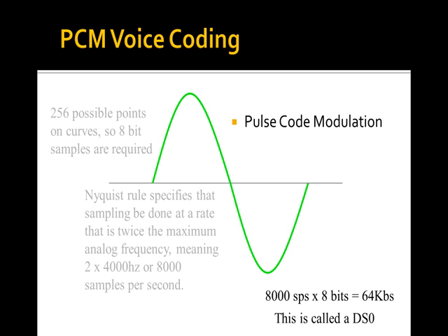So now, we've taken an analog audio signal that matches what's moving on the public switch network. We have coded it to a digital form that we can send across a digital transmission system. We've defined a rate for that, 64 kilobits, and we've given it a name, DS0. This is the voice equivalent data rate. So everything I'm going to do in this system that's going to move the human voice, I'm going to do in a multiple of 64 kilobits because that's a voice channel. Remember, we're not doing data with this. This is voice. It's 1959, 1960. Internet's still about 8 years in the future.